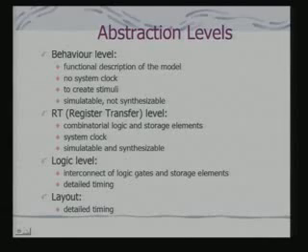If you think in terms of designing an FSM, what does designing an FSM mean? You identify the states, you identify the flip-flops required for the realization of the states, and then you require what? The input signals, and you design the combinational circuit to provide the input signals that would cause the state transitions, as well as identify the output signals required for driving your external circuit.